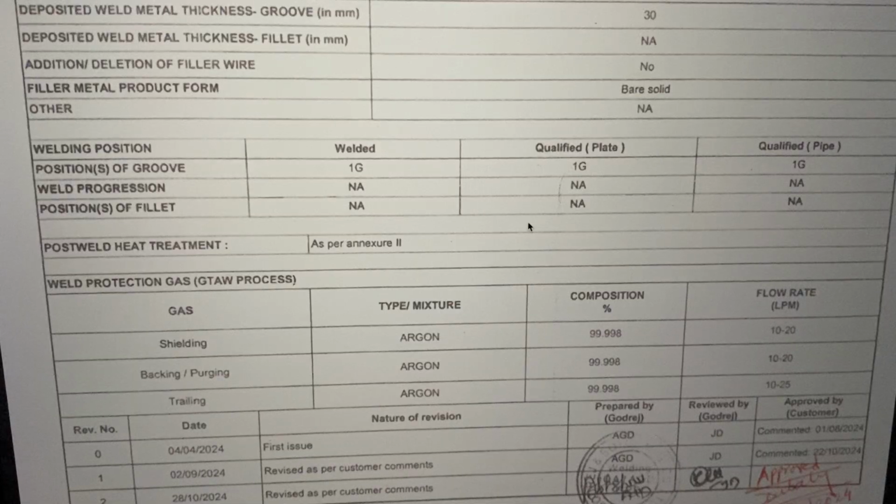So it becomes a very essential variable, and welder's qualification also becomes essential if we are going to do the non-favored, that is 1G, 1F, 2F positions. Other than that, it is very essential to have a welded plate in different positions in which we are anticipating the job to have, or the job is going to demand that kind of qualification.